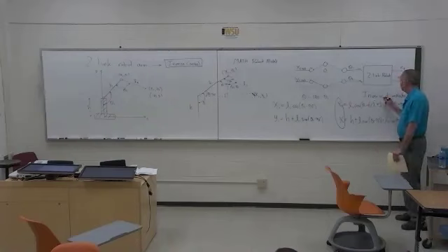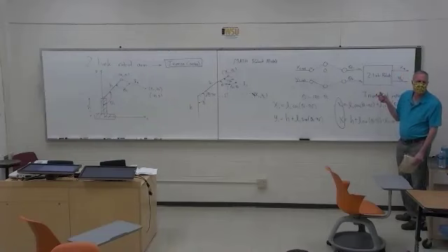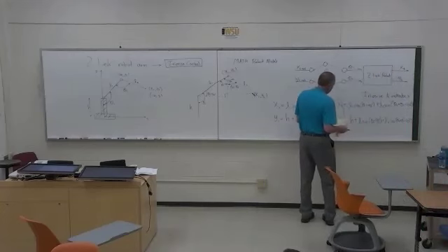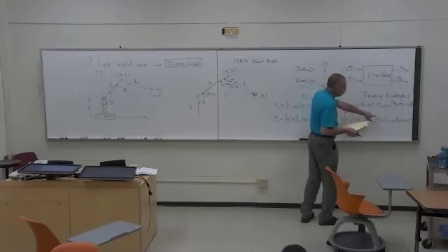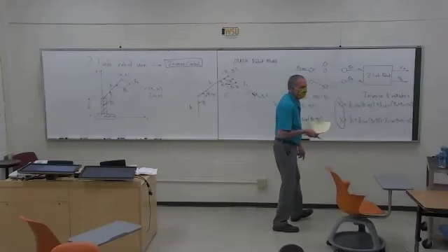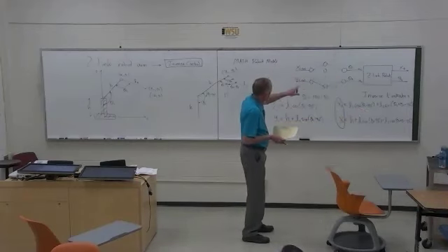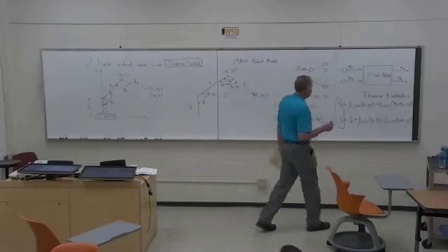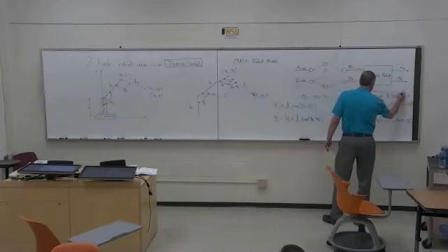But I don't want you to do that because the point of the equations is not to just solve it, it's to show the technique of inverse control. And maybe the model here is not 100% accurate. In other words, maybe the lengths you don't know exactly. And so we want this thing to learn to give us the values that the robot's actually given. So the equations, don't do that.